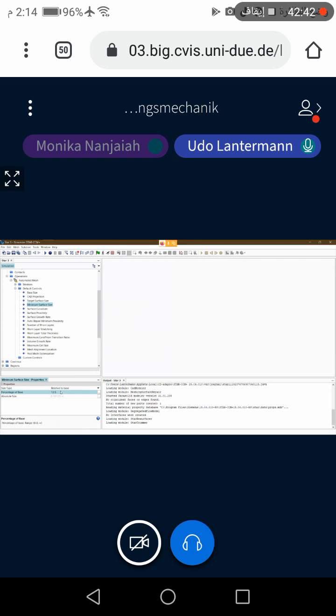Okay, so if you do the refinement later in your project, also always use this factor of 2. That means you have to choose your percentage. If 100% is the base size, then take 50, 25, 12.5, and so on. Or you can also enlarge it, and then, if 100 is the base size, you take 200 or 400 or 800%. Okay, so always take a factor of 2 for refinement, also for coarsening the mesh.